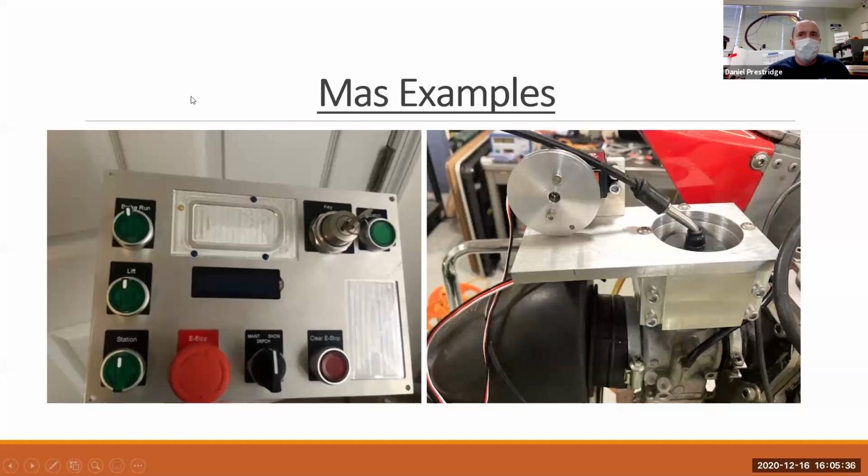But does that exist with you? Do you have those capabilities? If not, maybe try and make everything 4 millimeter capable. Can we put 8-32s in here or 10-32s instead of 3.5? Is there a reason why it's so small, with such a big difference? So think about that when you're moving forward. With this guy,